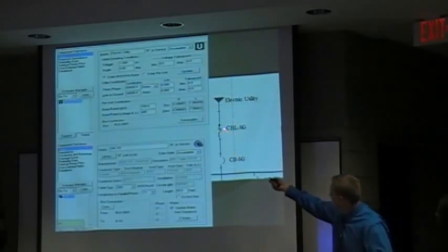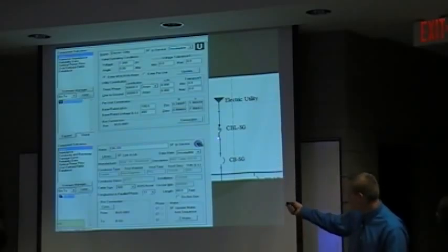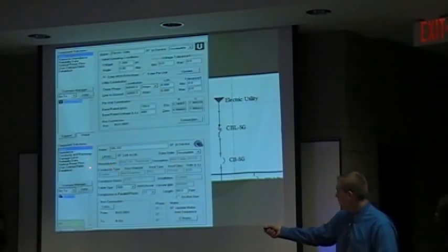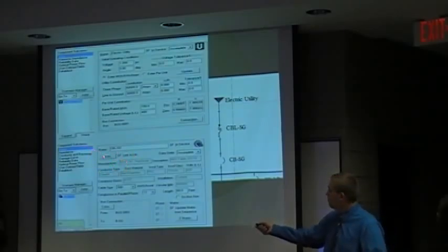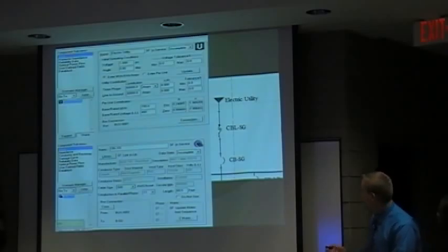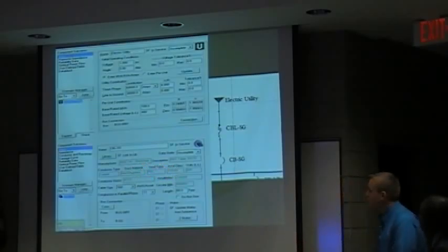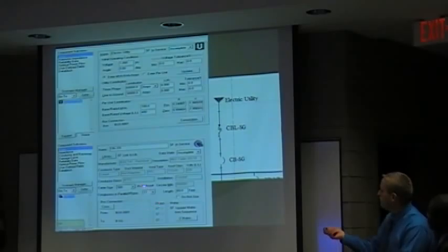And second here is the cable. This is another input device that I'll show, where you can click on that button icon to place it in Power Tools for Windows. There's a button here for the library, and up would pop all the different conductor sizes and types that you can input into this data. We put in a copper conductor type, non-magnetic, running PVC, insulation is THWN, and then we are running 4 conductors with the conduit.